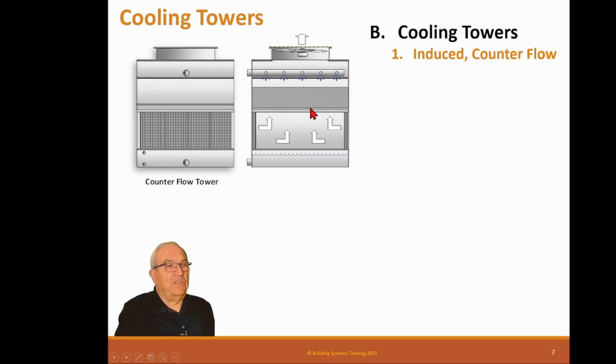But anyway, these towers basically have a water basin in the bottom, and they have a distribution basin on top, and then they have fill. This fill lets water flow down around it, and it wets the surface. Then as you pump air through this fan out here, it sucks in the side, turns 90 degrees and goes through this fill, and the water on the outside of the fill evaporates, causing an evaporation effect, thus cooling the water.